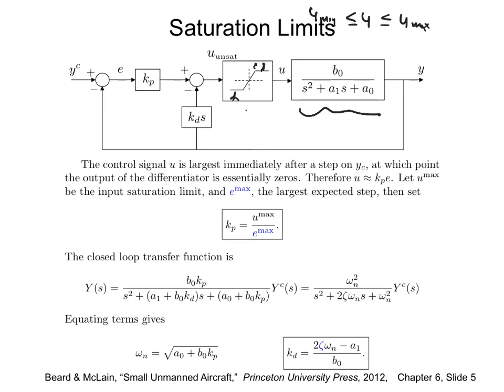So you can apply a saturation block such that we can keep the input coming from your PID constrained. And then you apply this PD control. So whatever Y we have, we have a commanded Y. So your error multiplied by Kp. So what is error? Error is Y commanded minus Y. So the error between what is commanded, what is desired, minus the actual output. So this is the general approach we will apply.